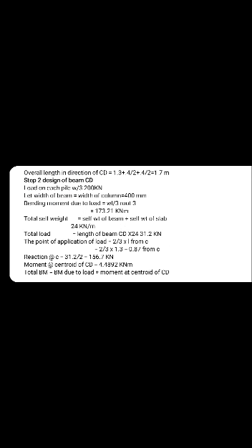Next, in order to determine bending moment due to self weight of the beam and a part of slab, assume the total thickness as 80 mm. Self weight of beam is calculated on the assumption that weight of slab is equal to 3 times weight of beam and adds with the beam.